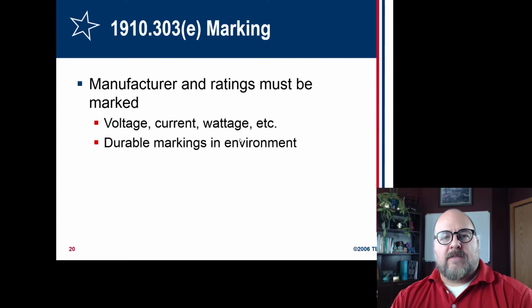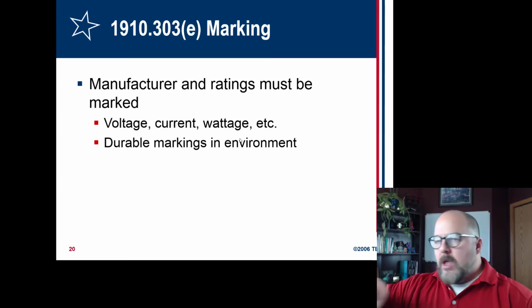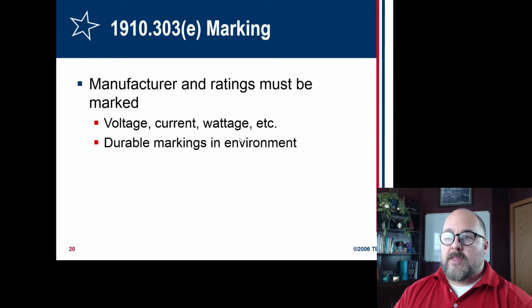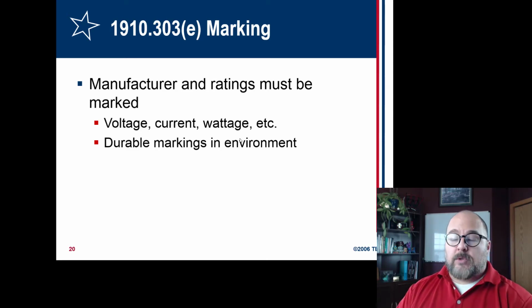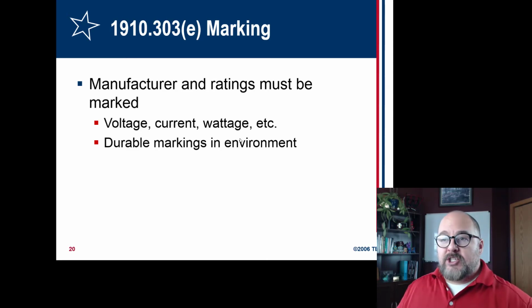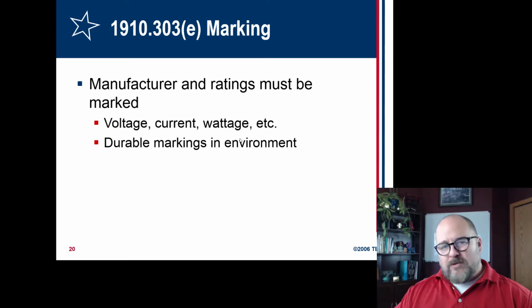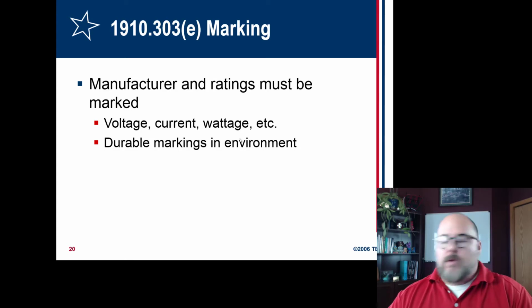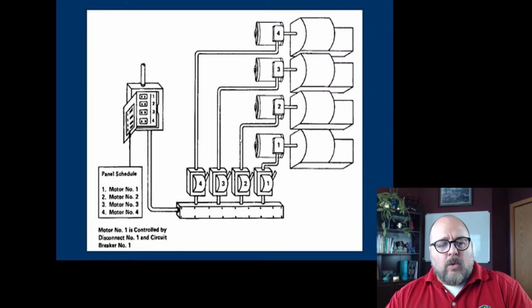But when I looked on the back of the commercial coffee maker, it was not designed for this. It would have overdrawn the device. So luckily I caught that, and it just happened to be luck that I looked behind it. Though I always look for electrical things, because especially in kitchen areas, I'm checking for ground fault circuit interrupters, which will come up later.